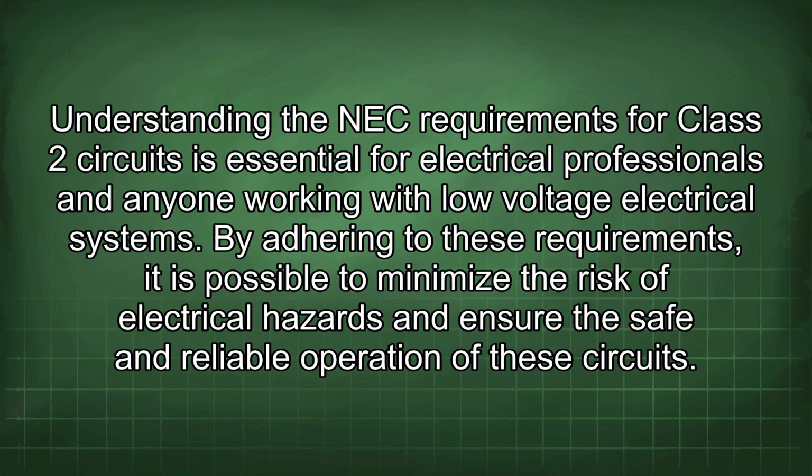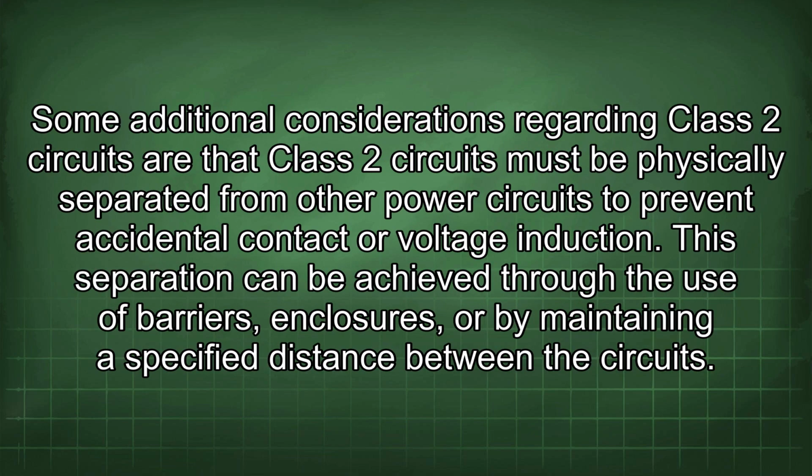Understanding the NEC requirements for Class 2 circuits is essential for electrical professionals and anyone working with low-voltage electrical systems. By adhering to these requirements, it is possible to minimize the risk of electrical hazards and ensure the safe and reliable operation of these circuits. Some additional considerations regarding Class 2 circuits are that Class 2 circuits must be physically separated from other power circuits to prevent accidental contact or voltage induction.